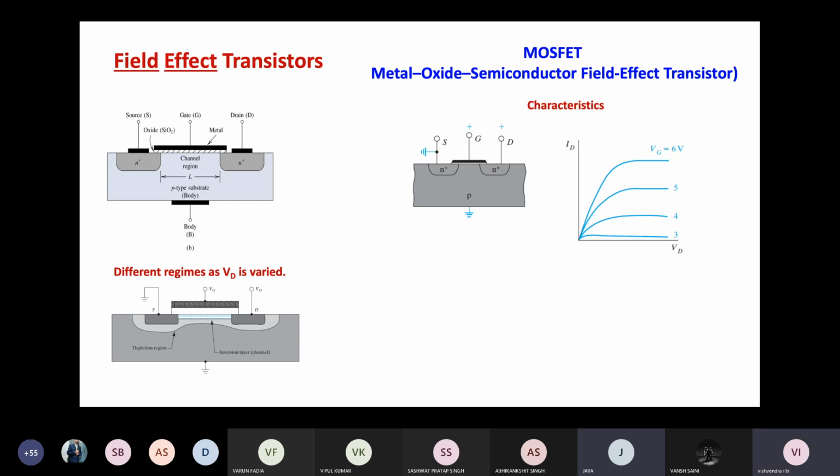Because we need to build millions of transistors, and almost each of our laptops might have a billion transistors, and we need to make all the transistors pretty much exactly the same, or consistent to a certain standard. If we have interfacial charges, or mismatch at the interface, then no two transistors will be the same, and this entire electronic circuitry may be dysfunctional. So is this part more or less clear?